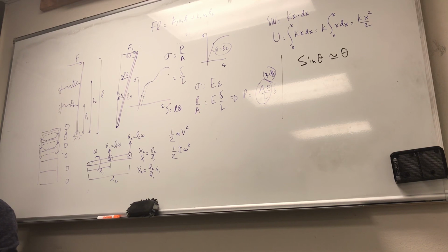This is the loading, right? And then if you get into the plastic range, obviously you're going to deflect in that region, right? And the moment you start unloading, why are we talking about unloading? Because this is a vibrating system. Force goes and then comes back and goes, and comes back. So as you unload, you're not going to come back here. You're going to unload this way, right? And then you have to go to the negative side because the force changes signs, right? And then you deform in the negative direction, and then unload back up, etc.